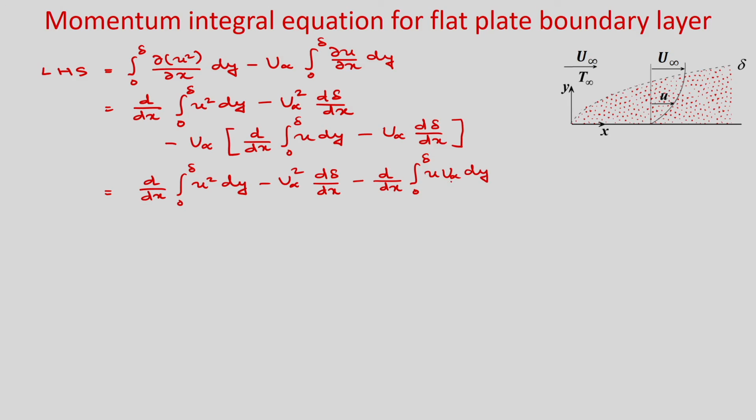I put u∞ inside this integral because u∞ is constant, so you can also take it inside the integral, and this minus and this minus will become plus. So, it will be u∞² dδ/dx.